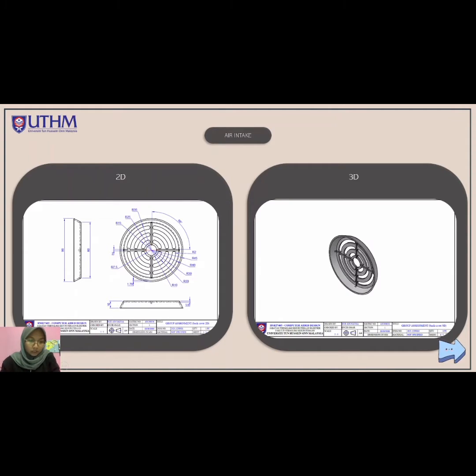After that, for the curve, I use the circle command, circle 10 radius, and using 2 millimeter radius, I set it to 2 millimeter radius. And after that, I trim the unused lines and extrude all the rectangles, this part, and it will become like this.